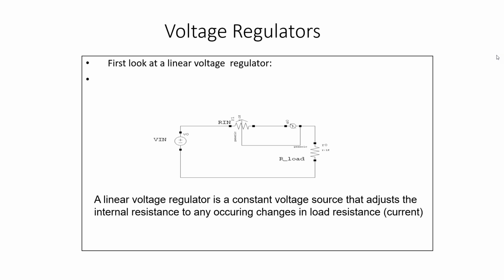Typically, let's say a mobile phone or anything, these are battery operated systems. Now, a battery, typically if you see a lithium ion battery, its output varies from 2.7 to 5.5 volt, right? And your digital core may be working at 1 volt. So you need some kind of interface, and you need a constant voltage for your system or SoC to work properly.